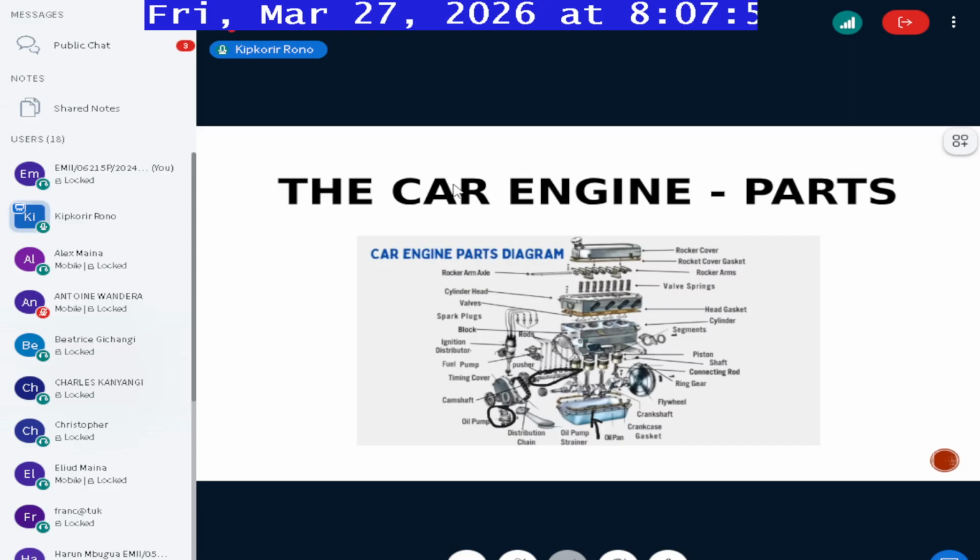so that all the parts that are rotating, especially at very high speeds, are lubricated. Because you can imagine the crankshaft could be rotating at even idle speed at around 800 rpm. That is a very high speed. You can convert that into angular speed in rads per second. Do you know how fast it is? So 800 revolutions per minute is very, very high, even at idle speed. And of course, if you were to just move, that idle speed will rush up to around 2000 rpm. So being at 2000 rpm when the oil has not properly circulated in the engine is not a very good thing. So it's usually just good to allow your car to